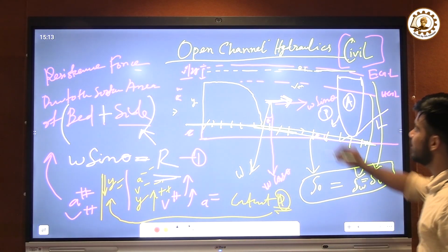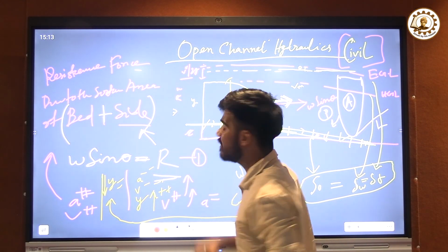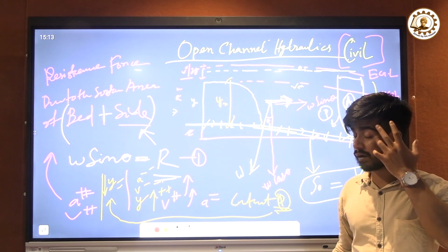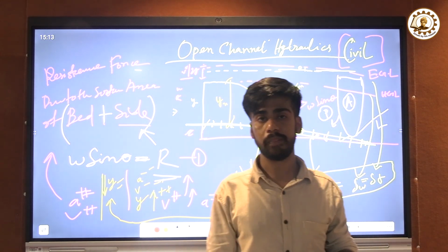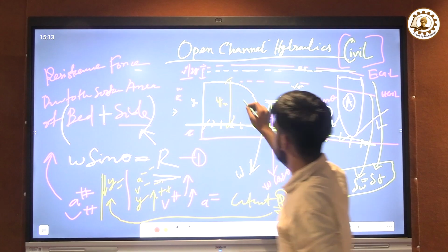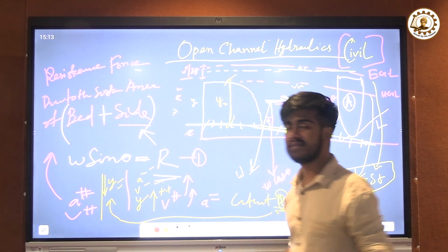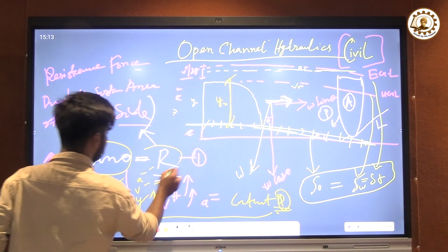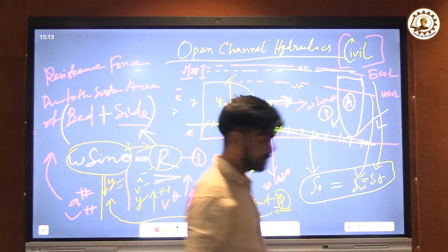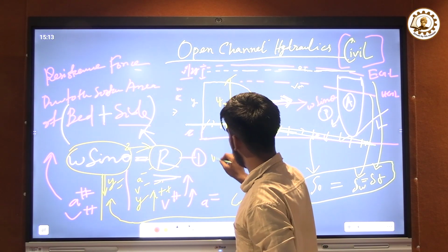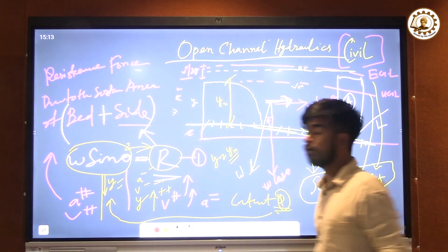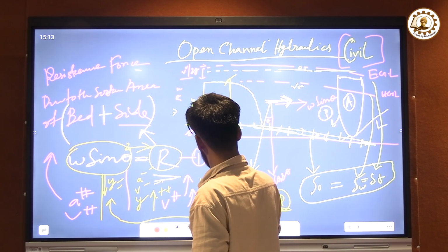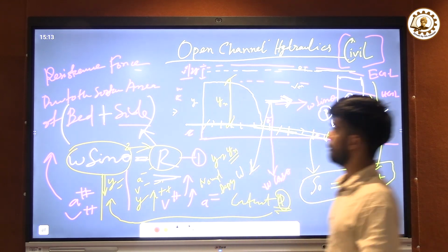Now, when the flow depth is increasing with respect to space or distance, then we can't just call it a uniform flow. Then when the flow gets settled and these two terms get balanced in an equilibrium state, then we get a depth of y equal to yn, which is called the normal depth of the flow. What is called normal depth.